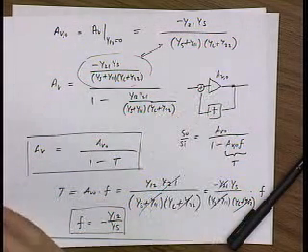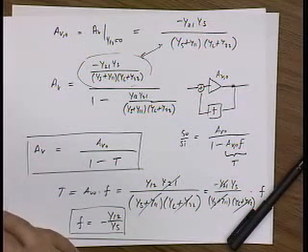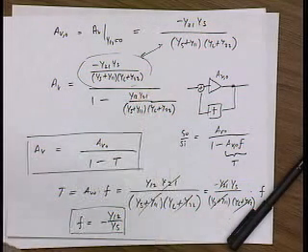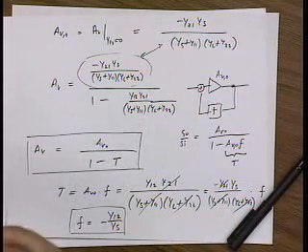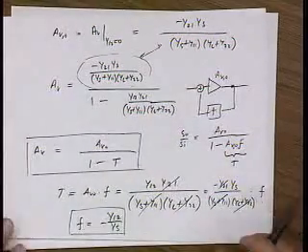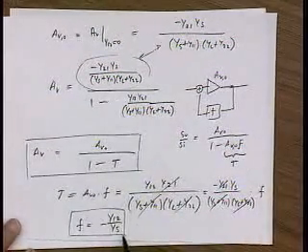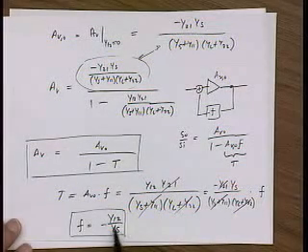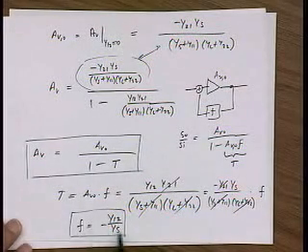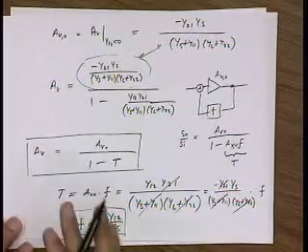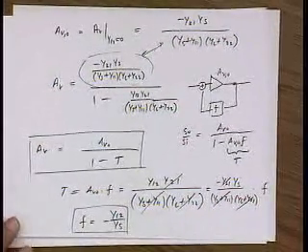We know this is shunt feedback, so this should be driven by current. And actually, we're going to see that come right out of the equations, right? In fact, you can start to see it now. You can see that if I drive this with a source resistance that's too low, the feedback becomes ineffective, right? You see that? We'll talk about that more explicitly in a second.